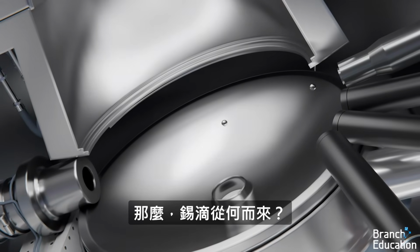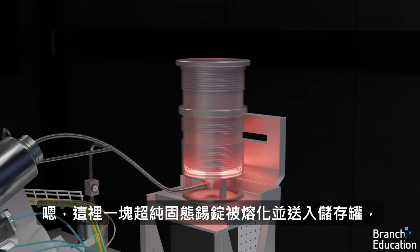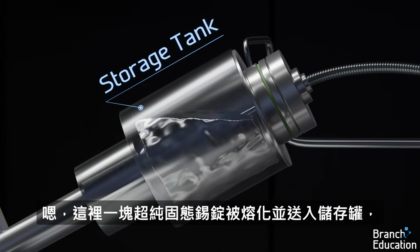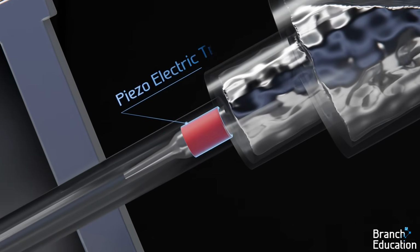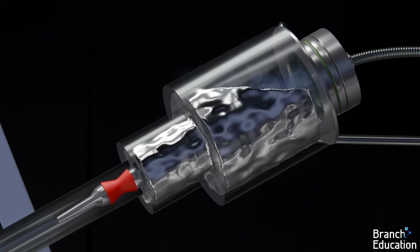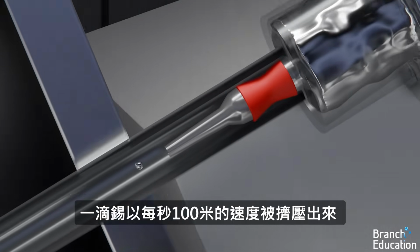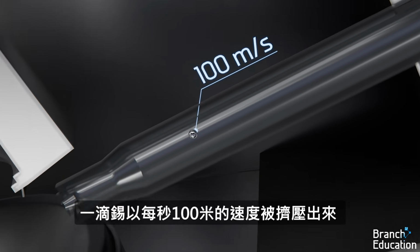So, where does the tin droplet come from? Well, over here, a solid ingot of ultra-pure tin is melted and fed into a storage tank and then piped towards a microscopic nozzle. A piezoelectric transducer squeezes the tip of the nozzle, and, due to high-pressure nitrogen inside the storage tank, a droplet of tin is forced out at a speed of 100 meters a second.